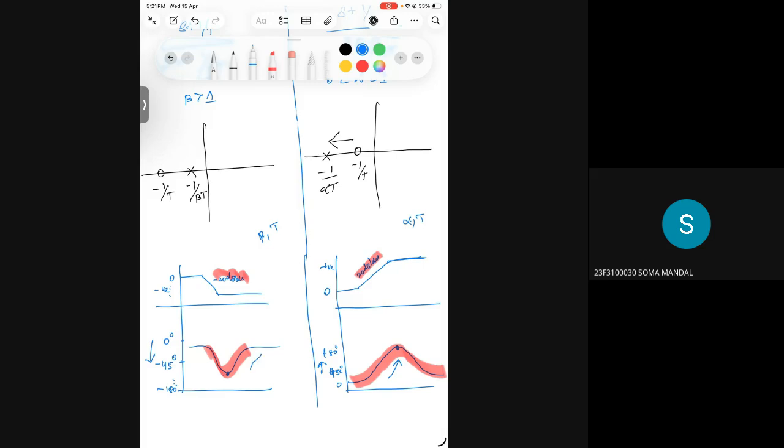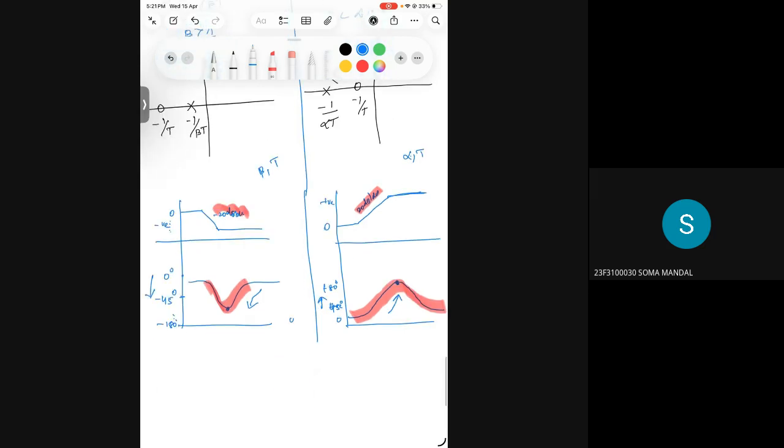Whereas it makes a dip in your phase, or it reduces your phase margin, so it is called a lag compensator. If you tune both together, we call it lead-lag. Whatever you learn for lead and lag will apply together as lead-lag. So you don't need to study lead-lag compensators separately. Just find the difference between lead and lag, then combine both for the third compensator.